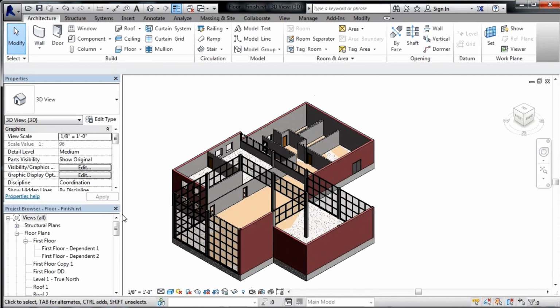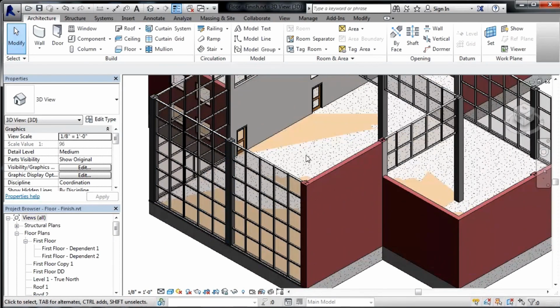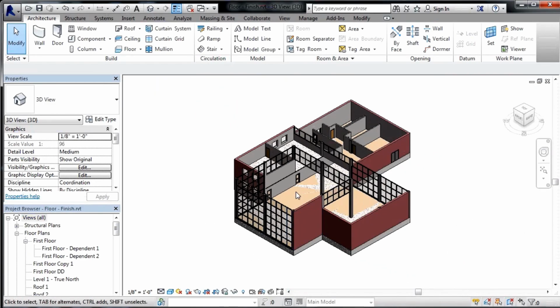Right now I'm seeing something which looks a little bit odd to me. That's the fact that I can see some color as well as some concrete. Both the concrete and the finished flooring look like they're actually at the same level, and that's incorrect. So we'll probably need to come back and make an adjustment to one of these floors so that they're at slightly different elevations. Before we do that, let's put a finished floor material up here on our second level.